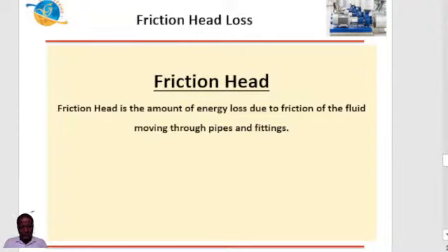And if you recall, I mentioned that it is advisable, by the time you are calculating your total head requirement, to calculate it based on an assumption that your suction tank level is empty, because at that point there is not enough potential energy coming from your suction into the pump.